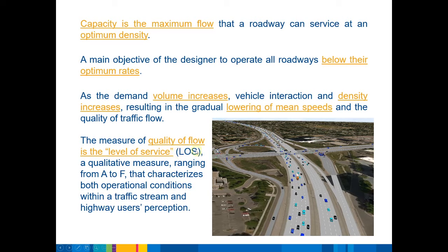Level of service, we can look up some definitions in road design manuals or textbooks in terms of vehicles per lane and that sort of thing. You can get these out of analysis software, so Sidra calculating the number of vehicles traveling through an intersection with signals or with a roundabout. That will also have a level of service and it will vary for different routes. So the north straight through approach on an intersection might have a level of service A, but the east-west straight through might be level of service D. So it can vary across different directions.